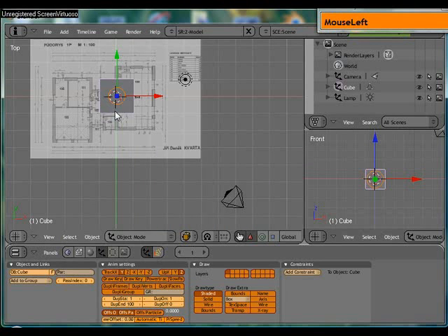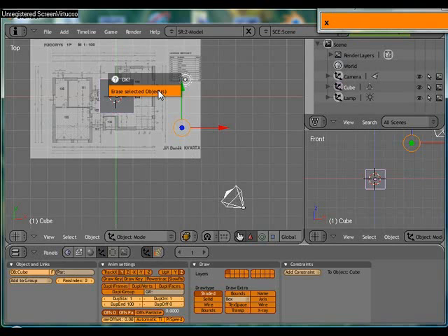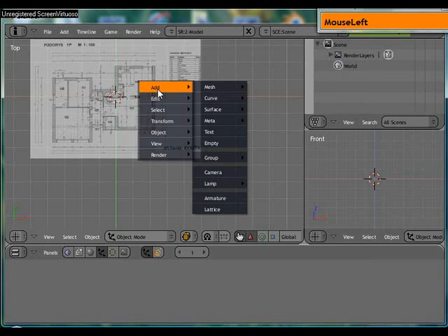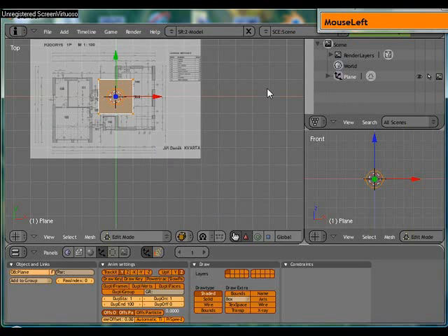And I need to clear the scene now, so I'll select all the objects by pressing A. To deselect any object if not all of them were selected, and now I can press A again, select all, X to erase, confirm, space, Add Mesh, Plane. I have now a plane, I'm in edit mode, so I can move it.